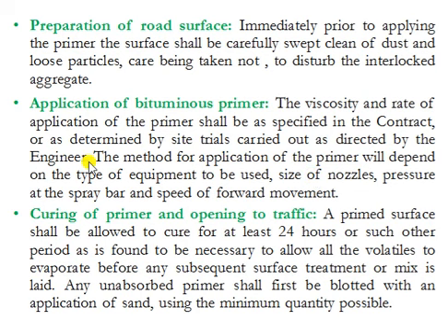And the next stage is curing of primer and opening to traffic. A primed surface shall be allowed to cure for 24 hours or such other period as is found to be necessary to allow all the volatiles to evaporate before any subsequent surface treatment or mix is laid. Any unabsorbed primer shall first be blotted with an application of sand using minimum quantity possible.